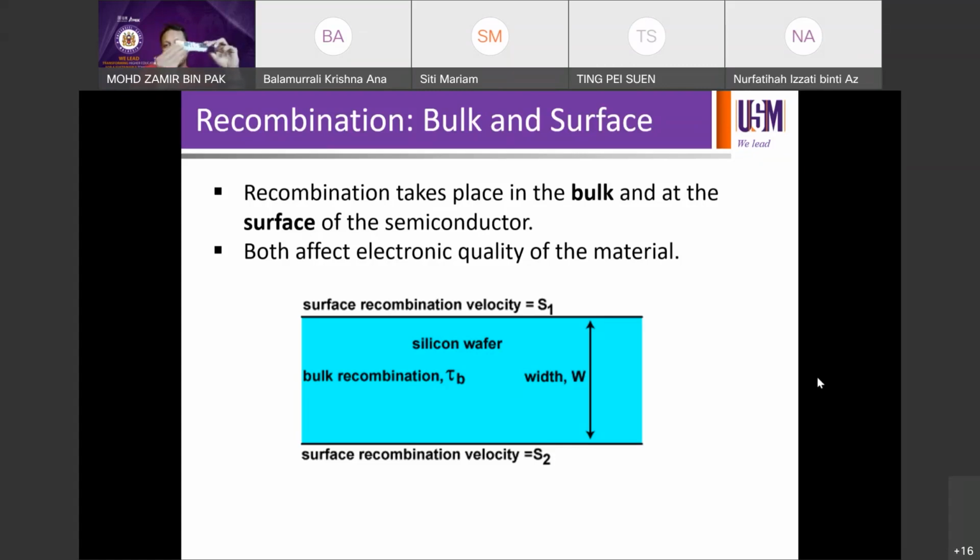To exaggerate a bit, if you work on a very thin device, for example 500 nanometer or 100 nanometer, but the surface area is the same, practically your device is dominated by surface only. The bulk is almost negligible. You practically have surfaces to work on, exaggerating a little. So when Bala said relatively, that's very interesting because it is relative. There is a bulk component, but relatively bulk becomes lesser and lesser, and therefore your surface will dominate.